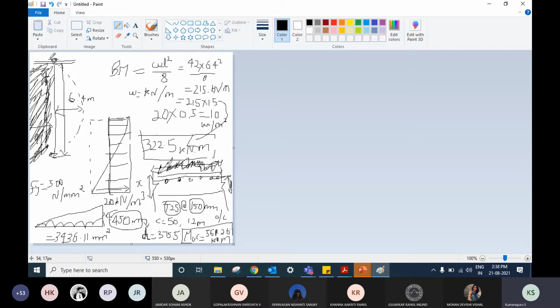So here for preliminary calculation, I told you, let's take a simple case example. But in reality, you could have some other slab joining here and there, right? That could give some sort of supports. So your entire bending moment, when you do an analysis in a computer simulated model, could be something less than the wl squared by 8 value. So for the actual true demand, we can again reduce the cross section size and the rebar diameters to optimize it.